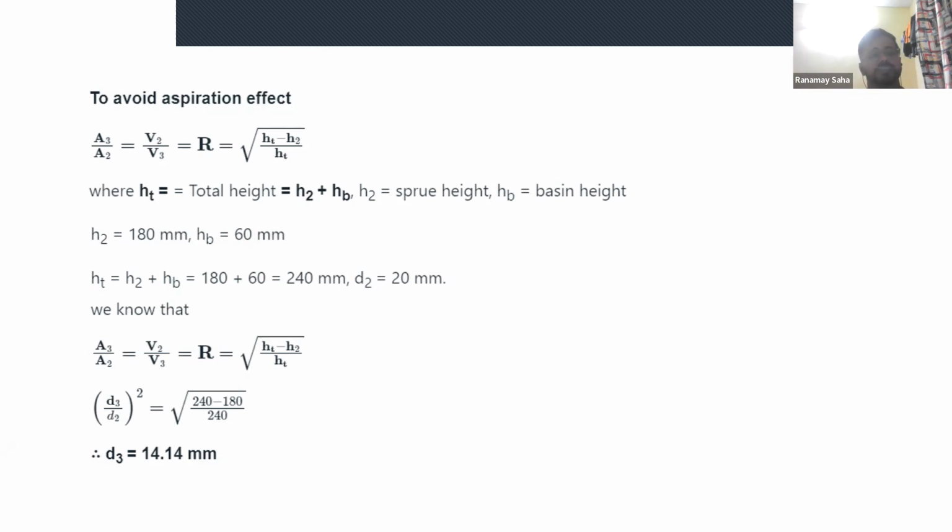But that is the interest of the design problem. It was seen that a trapezoidal screw would actually give the best result, but because of ease of manufacturing, we use a cylindrical screw.